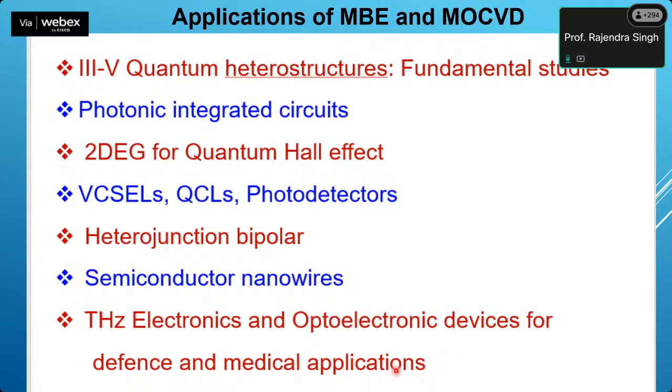So once you have this growth system with you, then you can grow epitaxial layers for various kinds of semiconductor quantum heterostructures, which can have applications even beyond quantum devices. That is actually the advantage of molecular beam epitaxy and MOCVD.